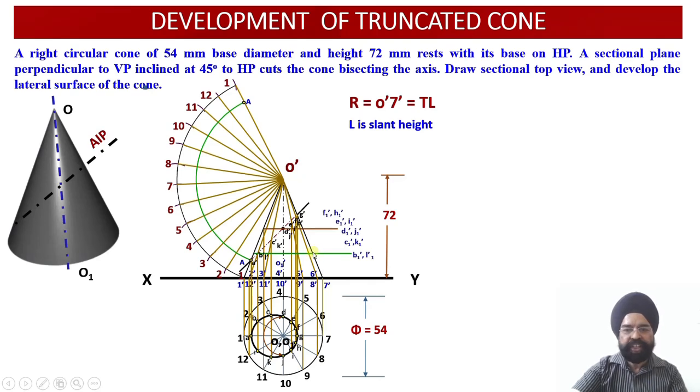So this point which is obtained, I call this true length as B1 dash and L1 dash. So true length and the apparent length, I have not marked the points over here because the space would have become very crunchy and interference would have been there. So I am going to mark either this point or this point, because both these points are the same, because this is also true length, this is also true length. So corresponding to points B and L, the arc will not be drawn according to this distance.